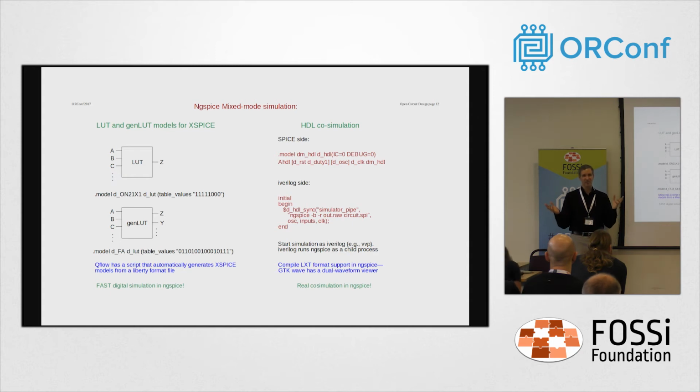The pad frame has probably disappeared. Very easy to make a pad frame wiring mismatch. If you don't verify that, then your physical chip doesn't match your iVerilog simulation. Better if you can take your entire chip design, extract a netlist out of that and do a full simulation on that netlist. So in order not to kill the simulators doing that, these are the steps that we've been taking recently.